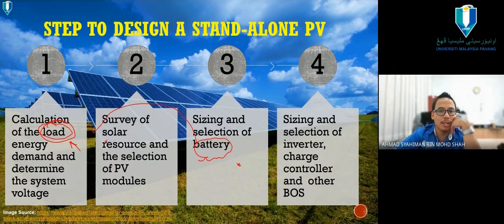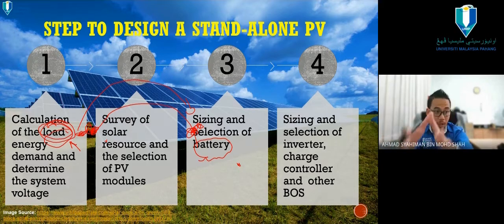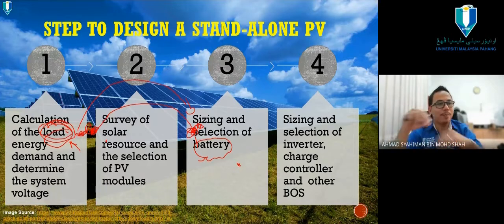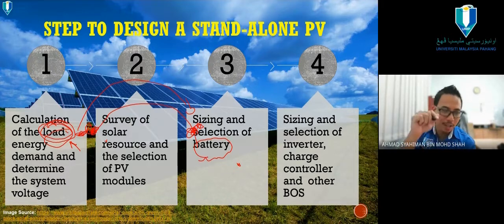These two are what I want to talk about, and I'm not that clever. If the battery is not enough, it's because the load is not controlled. The load is not relevant to the size of the battery we buy. We buy 100 Ah, but we expect to use lots of things. With a 100 Ah battery, you can charge your phone for several hours. For charging, that is sufficient. But if you put on a fan, a TV, try to use a portable aircon, then it becomes irrelevant, when we don't really calculate the load. So for me that is the mistake.